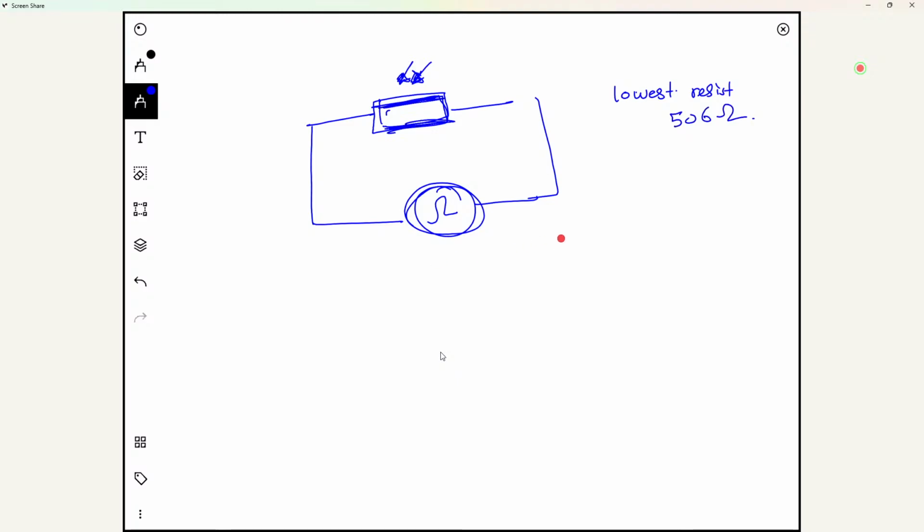So if you have worked with LEDs, you know that we need a resistor to protect the LED from high current. Usually we can use a resistor of around 330 ohms or so for a voltage of, let's say, less than 10 volts.